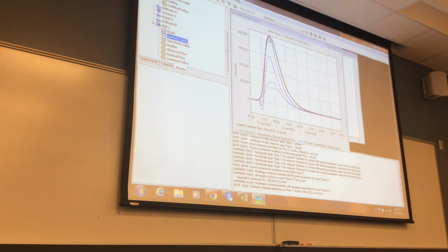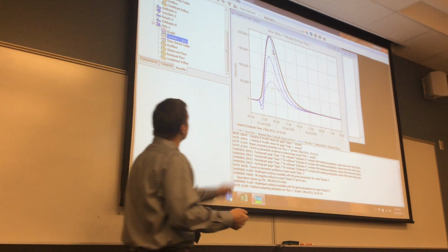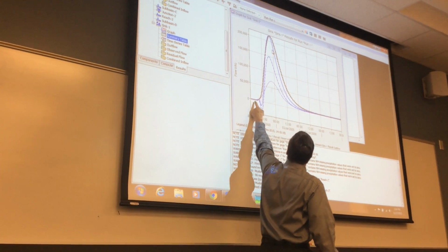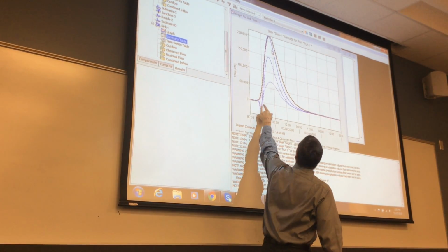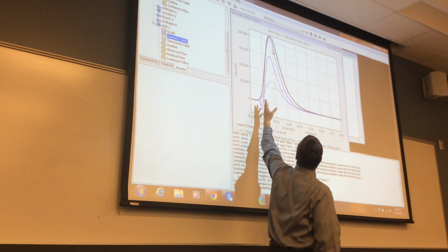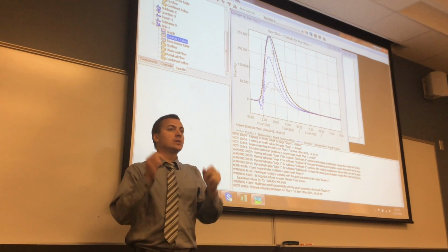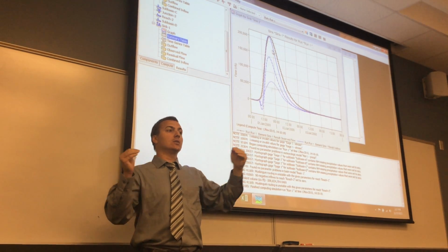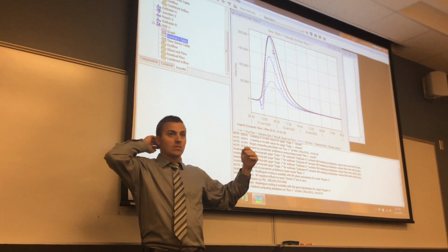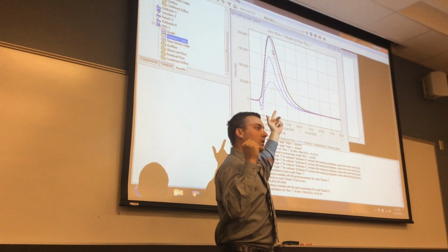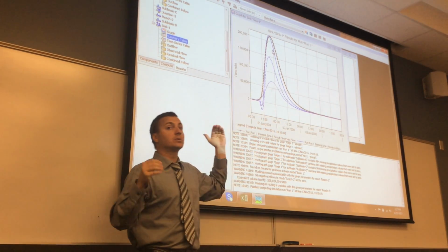Well, you can see here that our water is going out quicker than the actual measured data. See, our blue here, our watershed is draining too fast. So we have this weird behavior here, but it catches up. We might be happy with this, but it's draining too fast. So you want to increase the retention of water in your watershed a little. In terms of peak flow, we're doing really well, so your curve numbers might be okay.